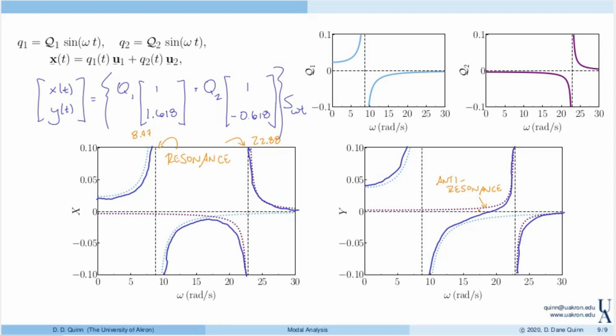So this is a quick introduction to modal analysis. With modal analysis, we are able to decompose the system into the response of the individual modes, even with forcing, and then we're able to reconstruct the response of the original system. In doing so, we turn a set of n coupled equations into a set of n uncoupled equations, which end up being much easier to solve. Okay, so again, just a brief introduction to modal analysis.